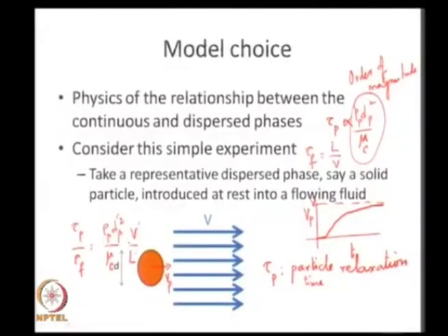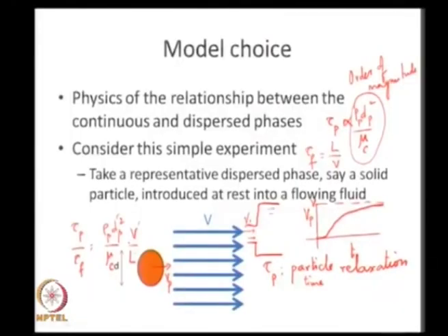Now, if I take the situation where I am dealing with little tiny air bubbles embedded in honey, and say for example, I allow the air bubble laden honey to flow through a little sudden expansion. You know that the sudden expansion process involves a sudden deceleration of the fluid, right. So, the fluid velocity is decelerated from some value V1 to a smaller value V2 here, and this deceleration is experienced by the air bubbles as well as the honey. The honey responds to it just like a single phase. My question is, do the air bubbles also respond to it as fast as the honey does?